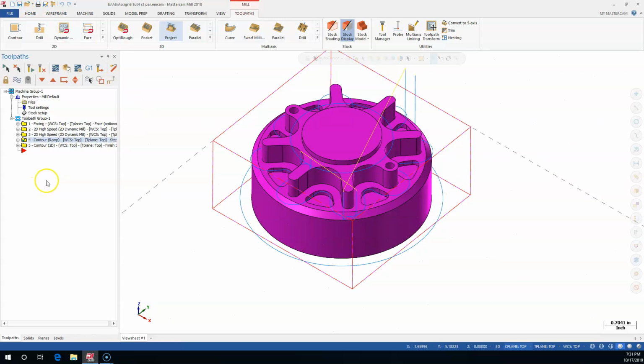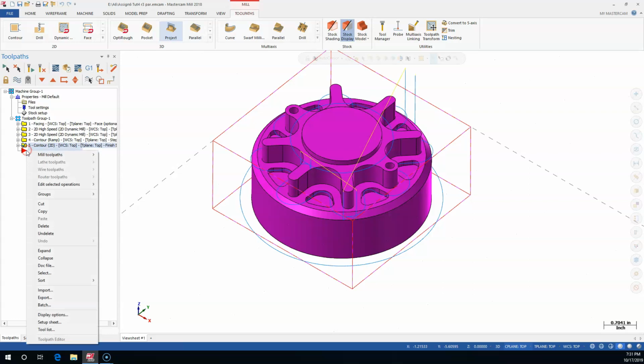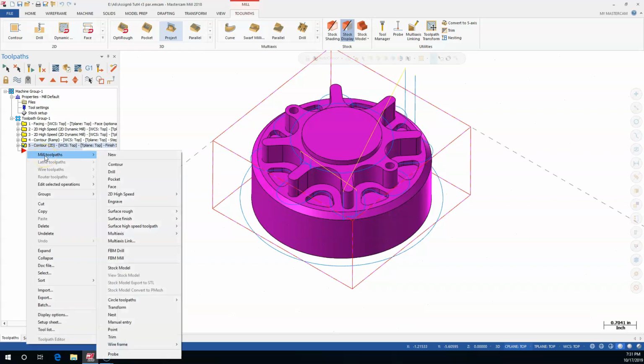And I was going to make a quick comment. I'll put it in the reminder to self, put it in the comments at the beginning, that in the 2020 software, the SolidWorks would open. And when we go to the machine to set up our machine definition, that was when it would crash. But if we saved it and closed it and opened it back up, then it would accept the machine. So there's still some issue going on with my solid parts, maybe not everybody's, but it didn't like my solid parts. So we're staying with the Parasolid file on this one.